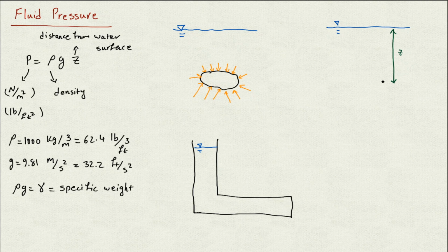And then I want to calculate the pressure for these points sitting here. You see there's a very small amount of water on top of that, but it doesn't matter. We always calculate the distance to the water surface. It's not important whether there is water on top of that or not, as long as it is under the water. The z is calculated from the water surface.